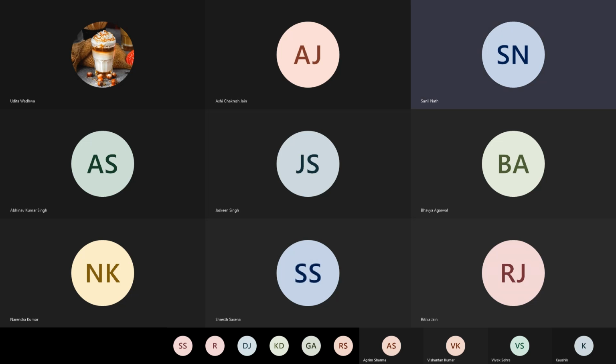So this dashed line is the enthalpy change from T initial to T final, even though the reaction was not carried out at 298 Kelvin. That's the total delta H change. And what we said is if it is a constant pressure process or a flow process, Q is almost equal to delta H, because you're just neglecting the shaft work and the kinetic and potential energies, which are generally negligible compared to all these heats of reaction and enthalpy changes that you've calculated, because they would very often be 99% of the entire heat effect.